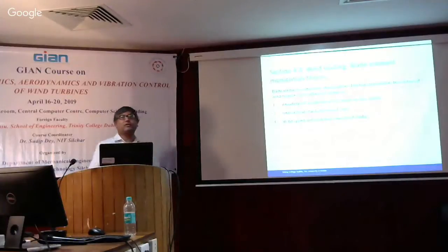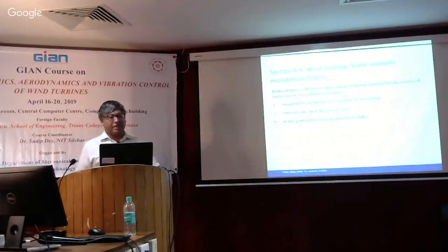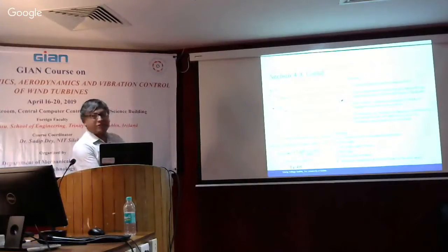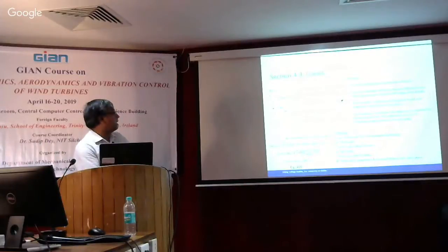Next we use the blade element momentum theory, which we have already studied yesterday and today. We take the properties of the blade, the geometric characteristics of the rotor, and the wind speed and velocities, and we do the same thing as we discussed this morning. If we do that, we get the load coming from the blade. If we integrate the load on the blade, we get the total load. But we also have to take into account what is called the generalized loads, because we want the loads associated with the mode shapes, the modal loads.